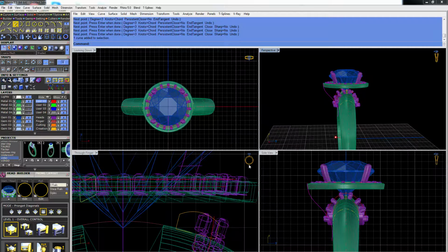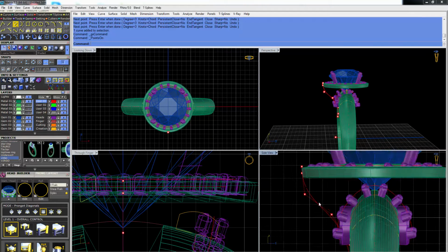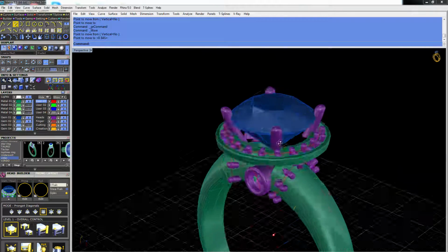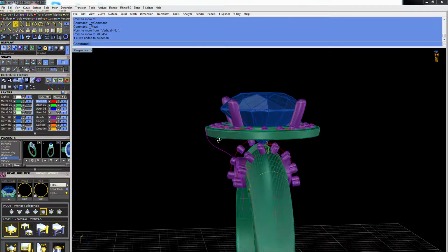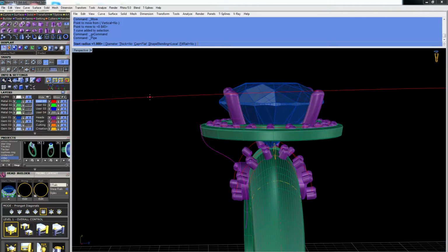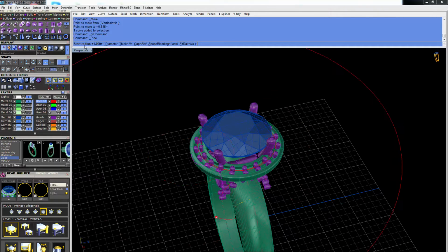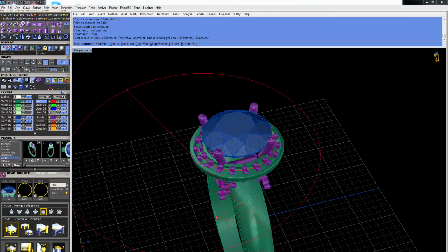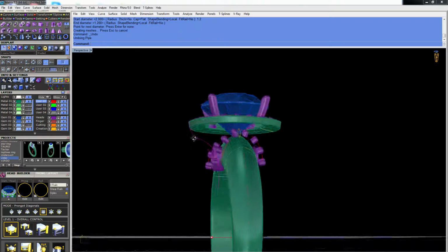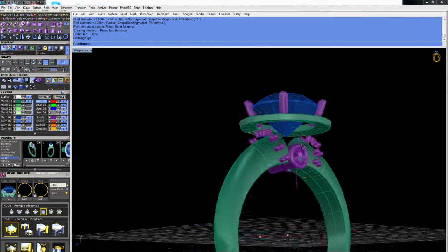Well, I don't want it so open, so I'm gonna check control points, get that control point and move it. I'm gonna move it up. Okay. Okay. Now let's make that support, that claw. If we just make a pipe, which is solid here, it's gonna be sort of boring, because for instance radius, let's say diameter 1.2. Okay, that's gonna be really dull. So I want that support to have an interesting shape.